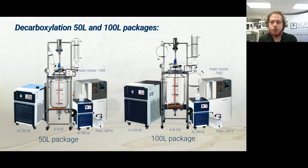To break down this package a bit, we would have a dynamic temperature control system, such as the Unistat T305s, in order to heat the jackets of these reactors. Then a recirculating chiller, such as the Across International C30s, for the condenser. Ideally, you'd have a cold trap for additional condensation capability and surface area to protect the vacuum pump, which allows you to lower the boiling temperatures and in general seal the reactor.